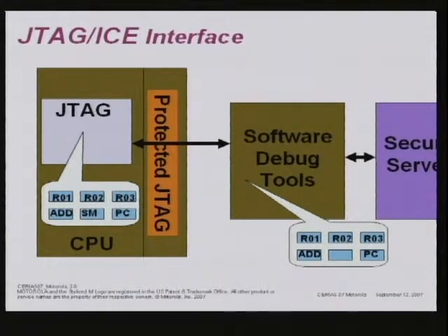So for instance, now we not only have the ability to control that connection point, but I can control levels of access. For instance, I can give Joel, who is sitting there, access to be able to see registers 1 through 10, but maybe not modify any of them, just absolutely watch them. Maybe you can't control the program counter, so you can't change the way the program is flowing. You can just see some of the information. Maybe I don't let you see some of the key peripherals.